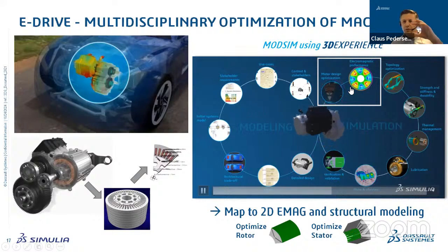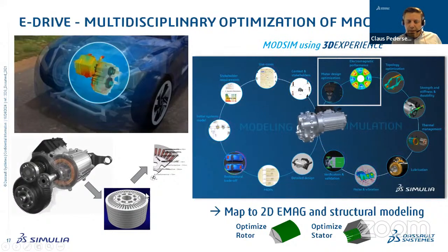So I'm looking at the first 2 steps, at the very initial conceptual design step, typically the step for topology optimization, as we know. And for the motor design, I will then look at the rotor. We can also look at the stator, both of them, but I'm just looking at the rotor here. And often we'll just make a 2D model. This is typically what you're also doing in verification processes. So we're neglecting the edge effects coming out here from the electromagnetic.